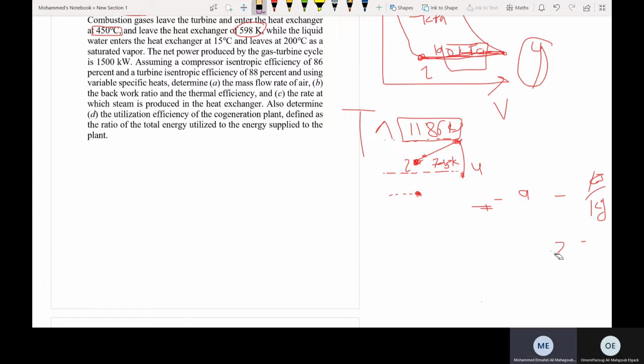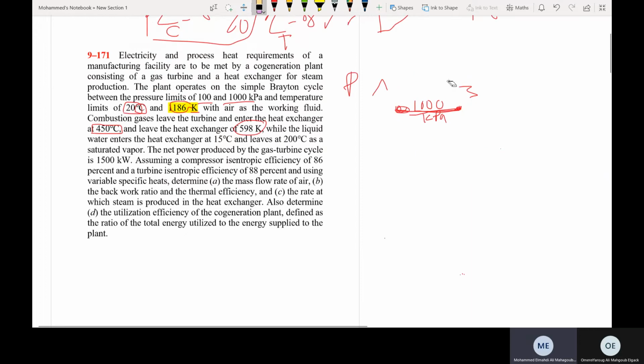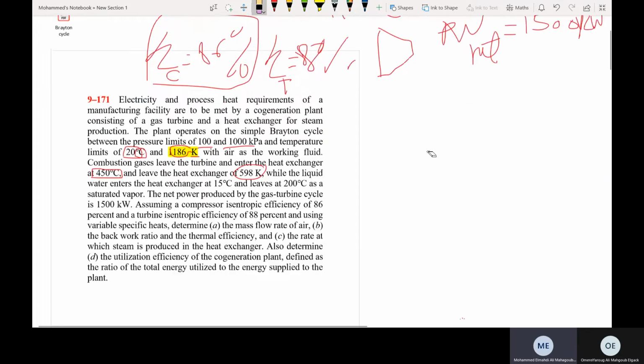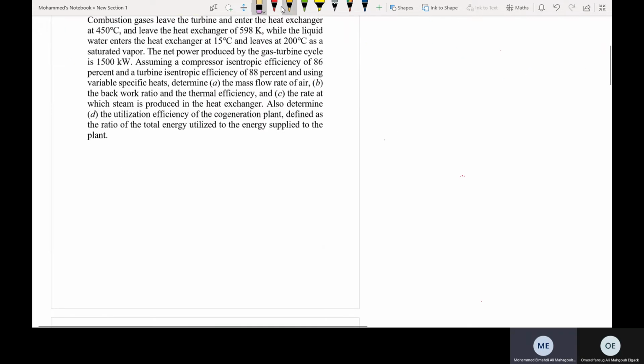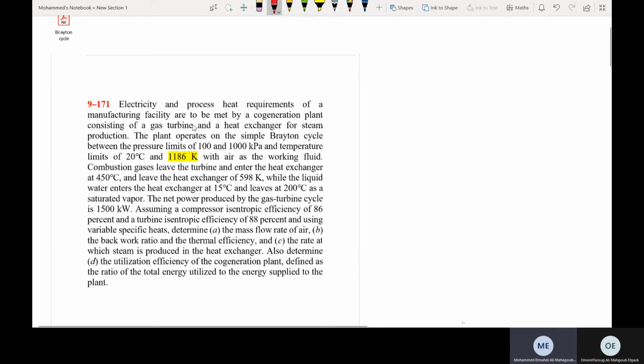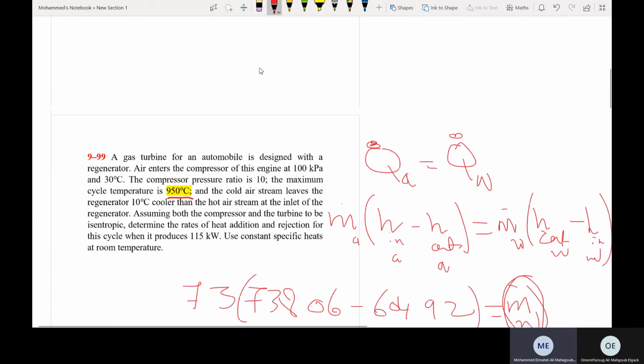So I guess this is maybe the hardest version of the normal Brayton cycle, where we made some utilization. But again, there is nothing else. You are just going to be given a Brayton cycle with the cold air assumption or a standard air assumption, maybe like this one. If it's called cold air assumption, then there is no need to go to the tables. And as I told you in the last tutorial, you are going to use the relative relations and get everything done.